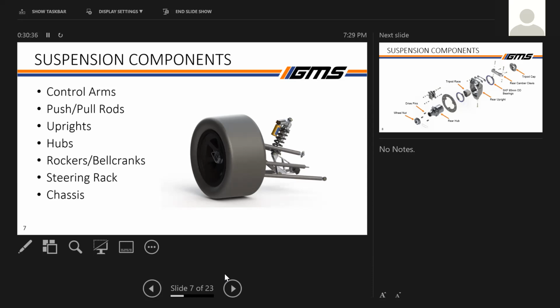I guess we could run FEA to do that, but with information on torsional stiffness of the chassis, we can estimate how much stuff is going to move around. What about the pull rods and push rods, how much they would deflect? Yeah, the members themselves. I guess we could run that in ANSYS, maybe do some hand calculations on it.